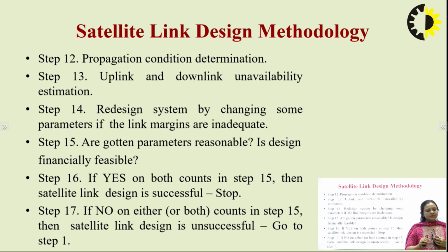Once the satellite has received the hello packet, it will again retransmit the same information, hello, to the ground station. Now it has again received the same packet hello. Now it knows that the satellite is available, or you can say the satellite is ready to receive your data. So in the next TDM slot, you can transmit your information. So that means by this procedure, we have established whether the uplink or downlink are available or not.